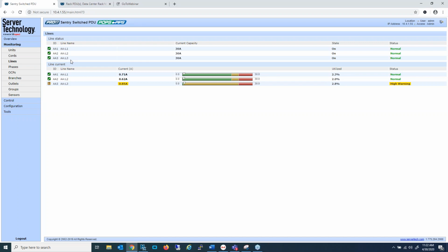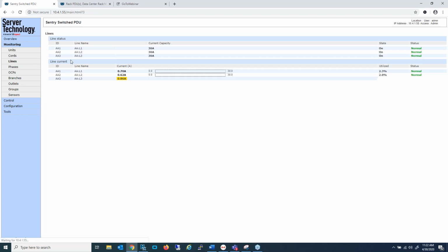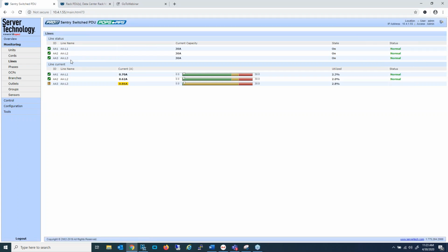You'd have to take a look ahead of time, make sure that the sum of the 2 different values does not exceed. If it's a line, in this case, you'd not exceed 24 in the example on the screen. And if it was a branch, you would need to make sure, which I think is what you were talking about, if you had different values on the A and the B outlets, because the device doesn't equally balance the loads, you would look at those loads, set the individual thresholds accordingly, but make sure that the sum of the 2 doesn't exceed 16.